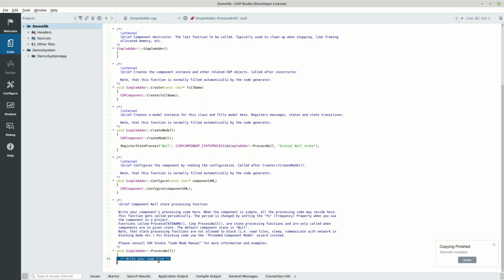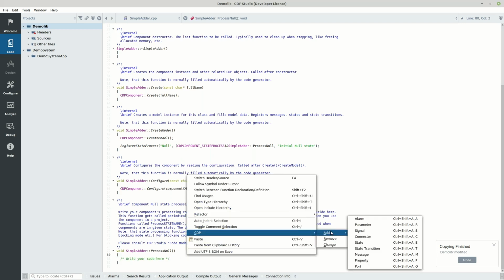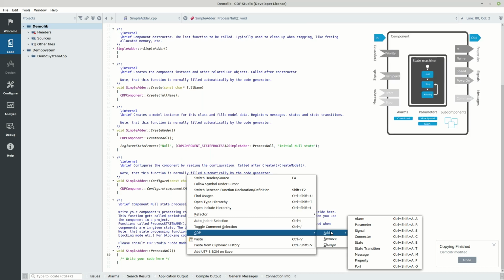The API of the code block is made up from smaller objects that can be added to provide ways to receive and send data to other code blocks, and to allow configuration of the block's behavior later during the system assembly phase. The provided code generator can make many different interface variables to cater for varied needs of data communication between blocks and for varied ways to do configuration. Signals are similar to wires between blocks. They are real-time values that are propagated automatically to other subscribing blocks and provide one-to-many periodic data connections.